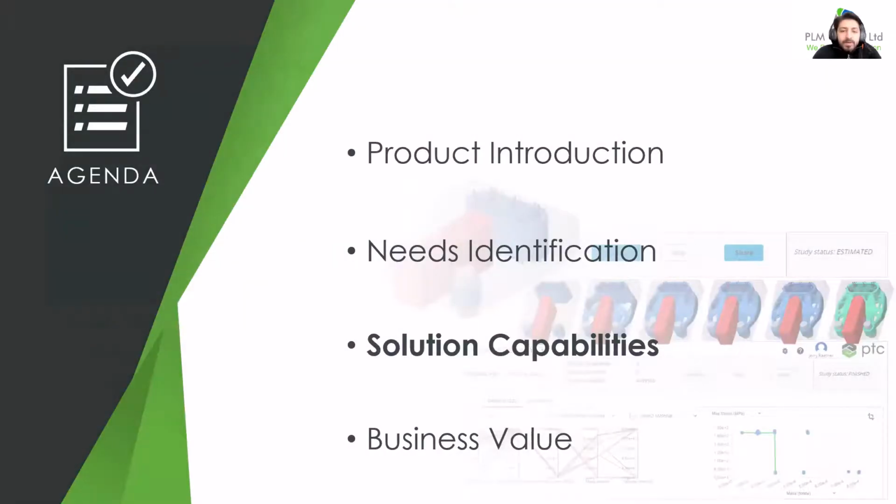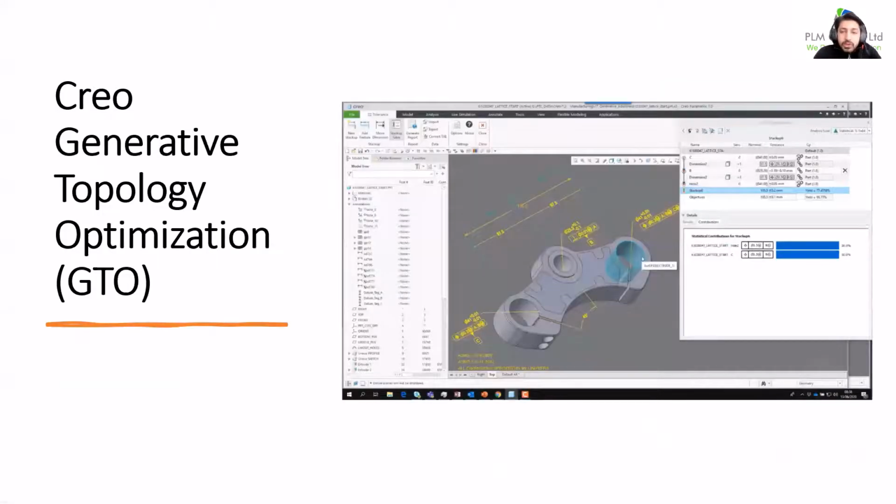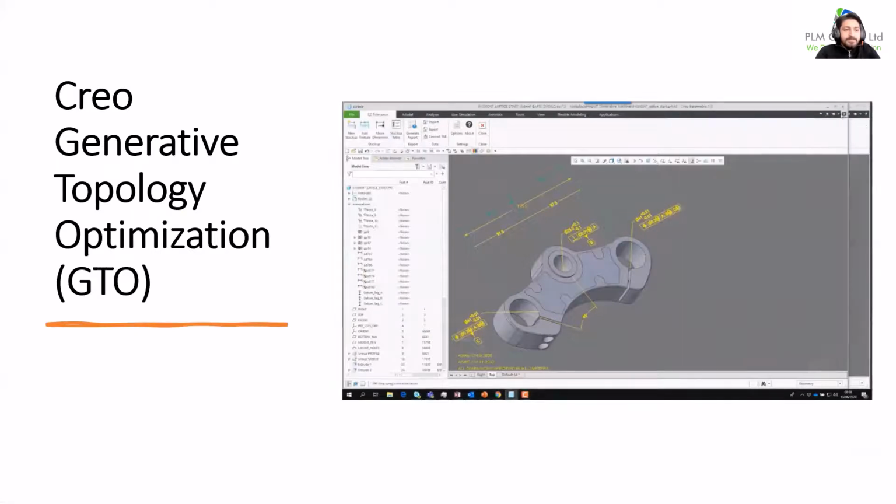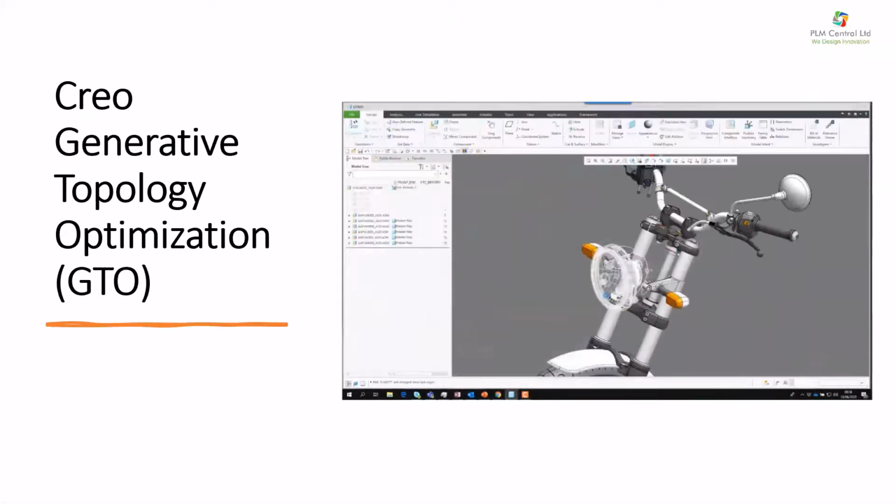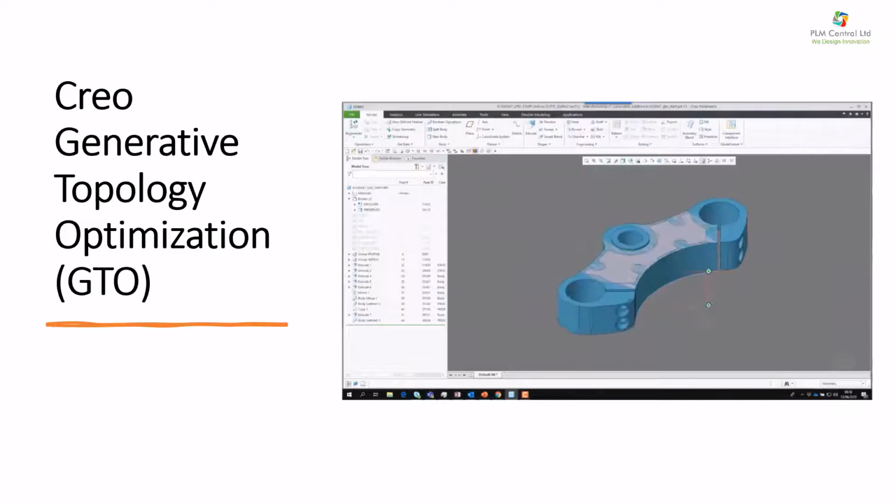Now, we've spoken a lot about what generative design tackles. Well, let's go through and show the solution in action. So the next phase of my design process then is to go and create a model. Something that was introduced for Creo 7 was the opportunity to go and create multiple bodies in a single part, and this lends itself really well to processes such as generative design and being able to define which areas are actually required for what processes.